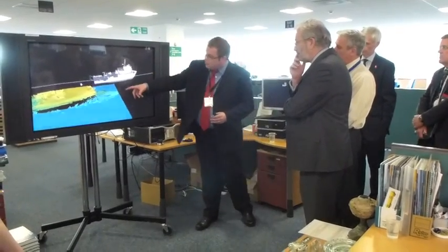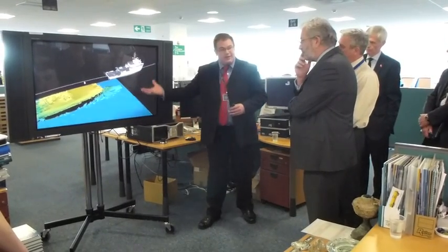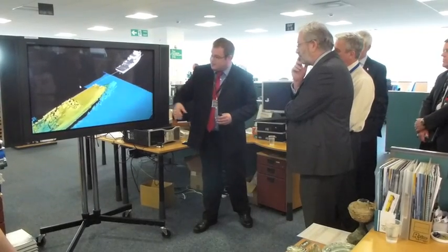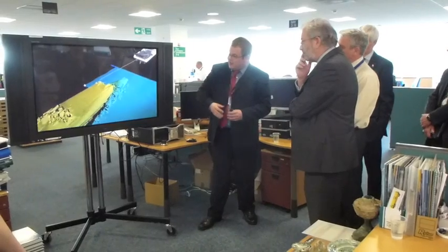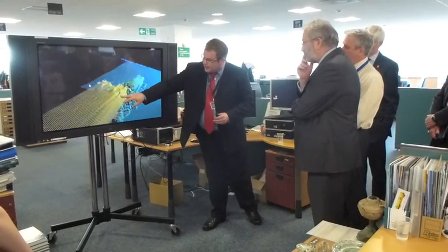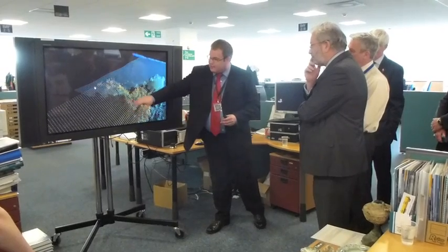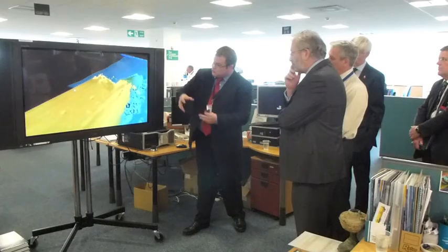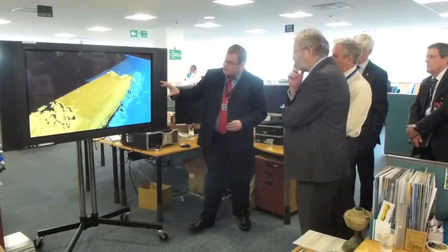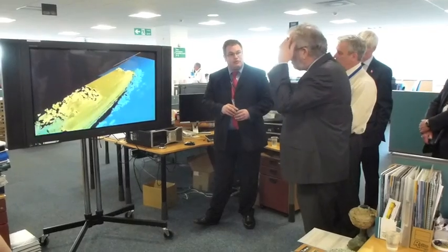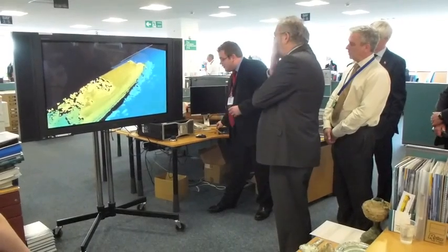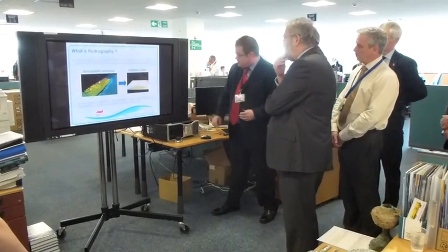The sound emanates from the bottom of the ship, which has a number of survey sensors mounted on the hull, and as the vessel proceeds across, in this case, a wreck, it's able to scan the wreck and geolocate where these various points are, so we know where they are in a 3D grid. And when we pull those all together, then we get these really nice high-resolution 3D models. So that's how we see objects on the seafloor.